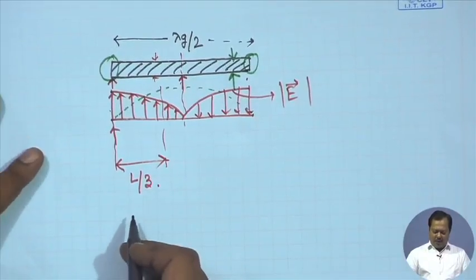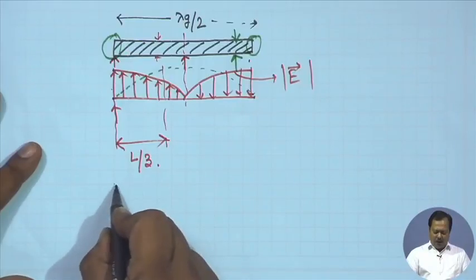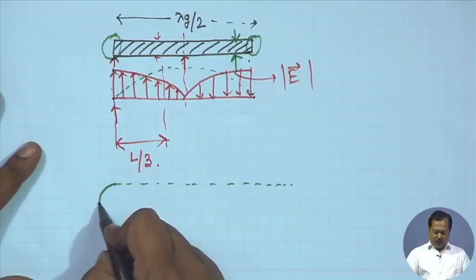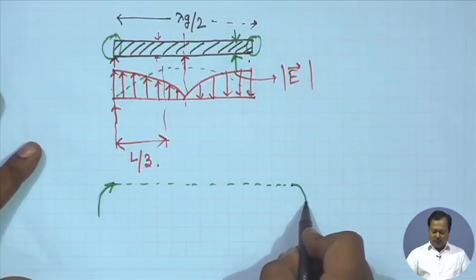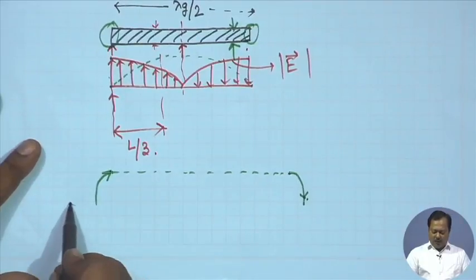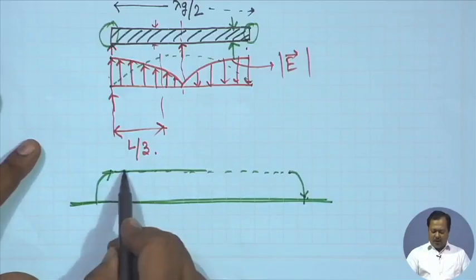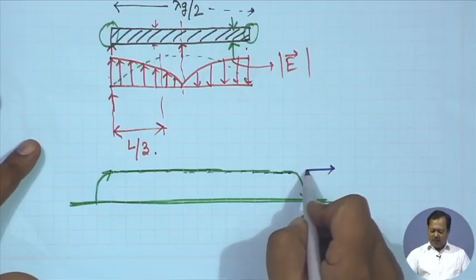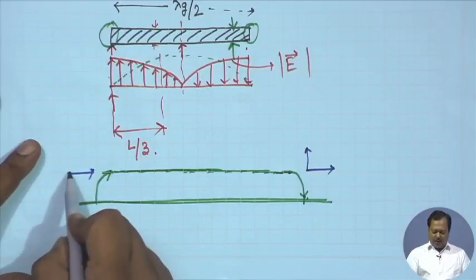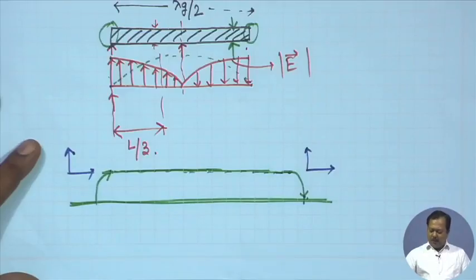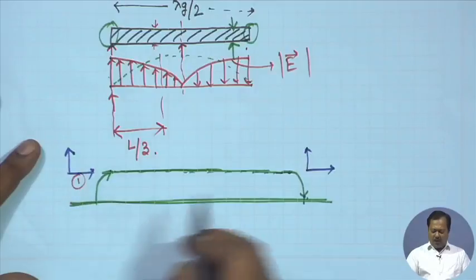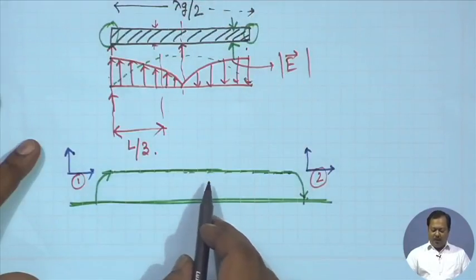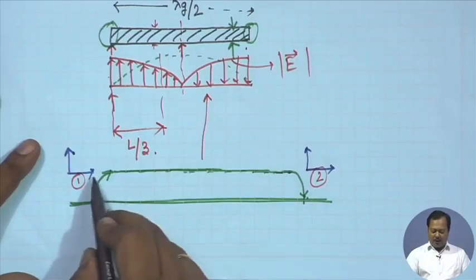Now, how do we have radiation from the fringing field? Obviously, for that, the electric field and magnetic field have to be in the same phase. So, let us say these are the fringing field components. I am drawing the side view. At the bottom we have the ground plane, and this is the top strip. Now, I can represent the fringing field along two orthogonal axes. In that case, we see that these two electric field components, let us say this is 1, this is 2, are in the same direction looking from broadside, and we will have maximum radiation intensity in the broadside direction from these two fields.